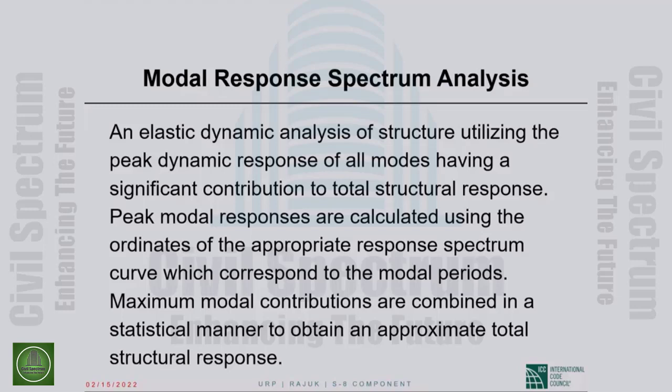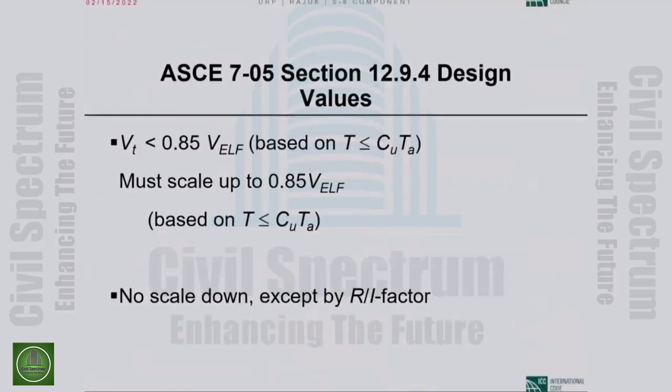But if the modal periods are close together, then we have to go to more complicated sums, the, what is it, CQC, anyway, complete quadratic combination, whatever. There are more complicated statistical sums that are available.